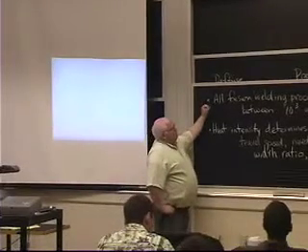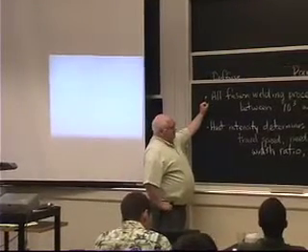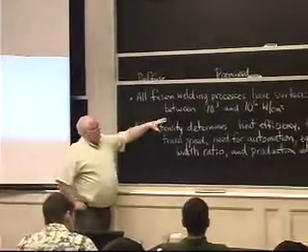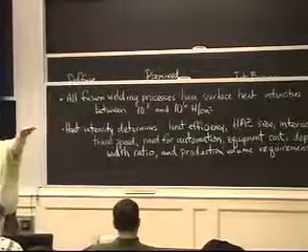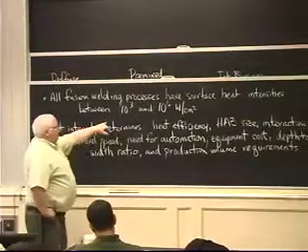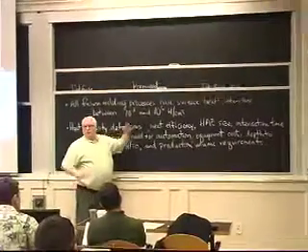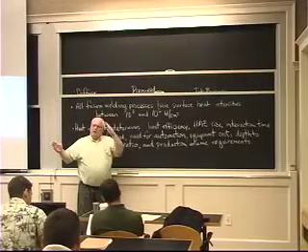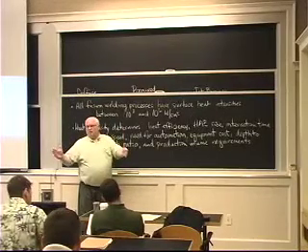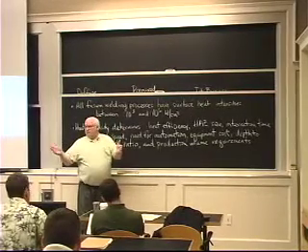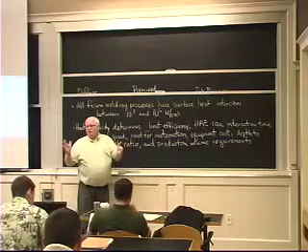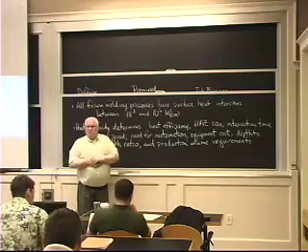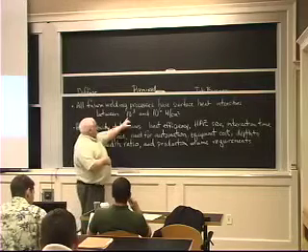But all fusion welding processes, last time we talked about this, in order to get melting, which is fusion, have to have surface heat intensities over only a 3 order of magnitude range. What I didn't tell you is about 1 order of magnitude comes between the difference between melting, just barely melting on one end, and severe vaporization on the other end. It's only about a factor of 10 in heat. To vaporize something takes about 10 times as much heat as to melt something. And if you want to know why, you can take my thermodynamics class. But that's a factor of 10.